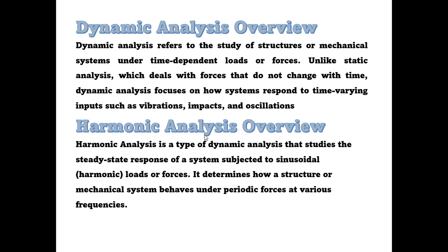Next, harmonic analysis. It is a type of dynamic analysis that studies the steady state response of a system subjected to sinusoidal loads or forces. It determines how a structure or mechanical system behaves under periodic forces at various frequencies. In harmonic analysis, we are going to study how a machine component or a structure will behave for different loading conditions at different frequency ranges. So that is what harmonic analysis means.